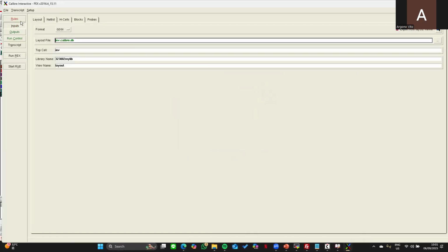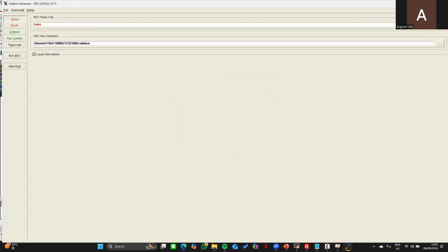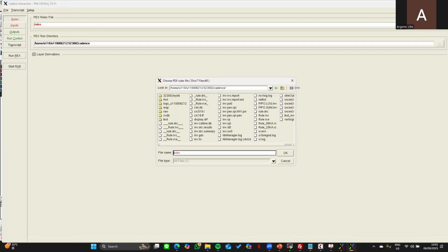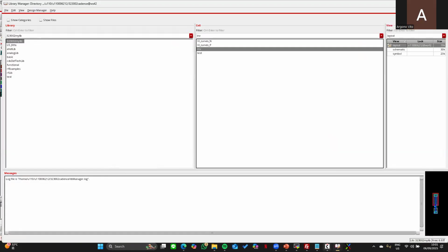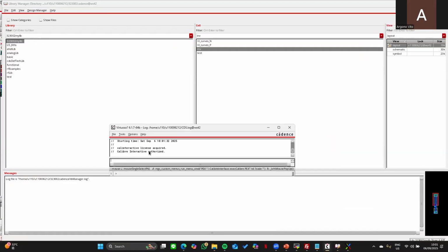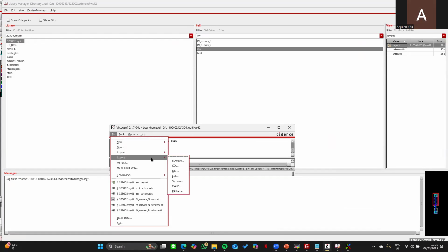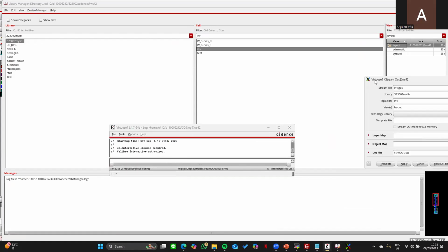So still use the rule in here. Oh wait, I need to export the GDS first. Okay, so you need to export the GDS first. It's in stream out.